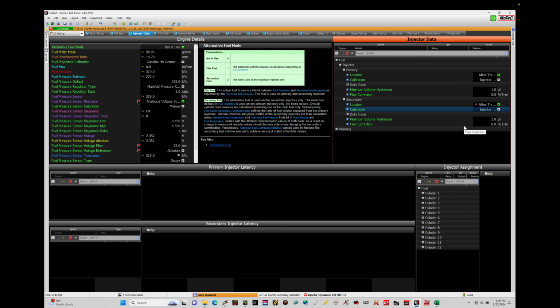So how we actually stage and bring those in terms of the fuel volume and the injector pulse width is important, because if we don't define the contribution percent, which is another table we're going to be looking at here in a few minutes, we'll find that when we're commanding the fuel flow into the engine, we're going to get to a point where, if we don't have that contribution percent correct, we'll have one set of injectors hitting 100% duty cycle before the other. And we want them both to have equal amounts of fueling contribution relative to their flow size.